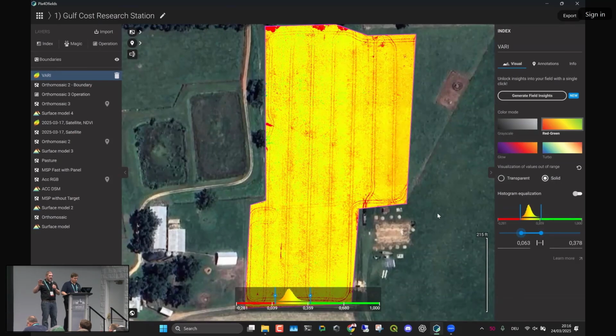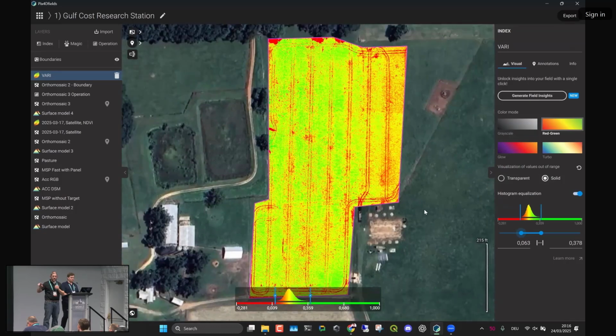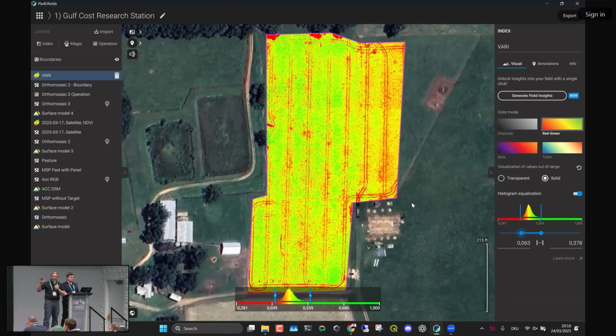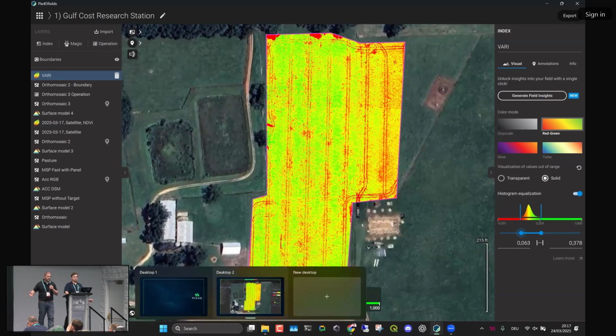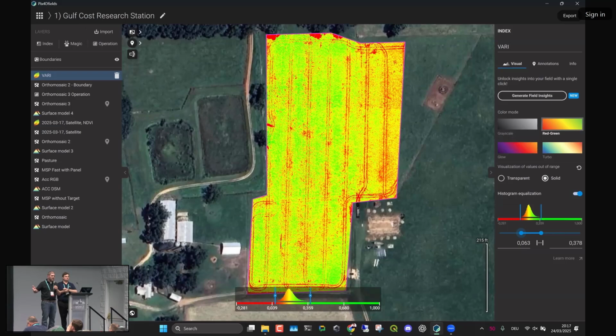This will save you a lot of time and a lot of headaches. Just trim what you're looking at so you're purely analyzing a corn crop, a bean crop, a pasture. Don't analyze the trees, the roads, all that stuff, because all you're doing is showing where the trees and the roads are, and that doesn't help you.